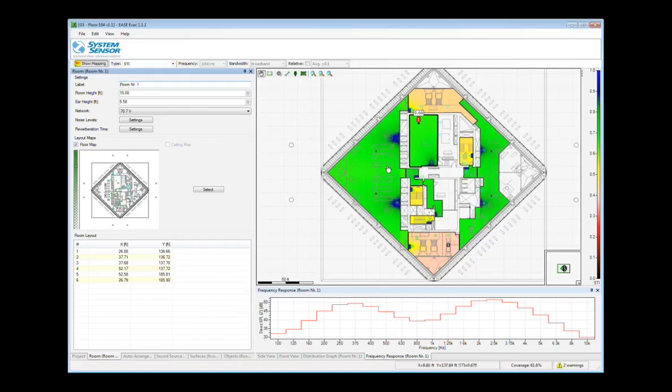And one of the things about ADSs is that it is typically used particularly when there are walls between the rooms, like there are in this case, where I've now got multiple rooms all separated and they all have separate loudspeaker systems in them. You can see that I've got a variety of different mapping colors on here. I have a couple of them that are, if I hover over down here, you can see down in the status bar, down here again, that my STI in this area is about 0.39, 0.4, 0.41, something like that.